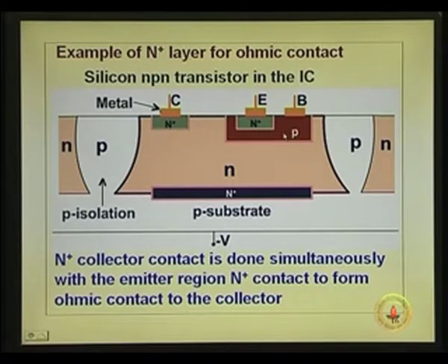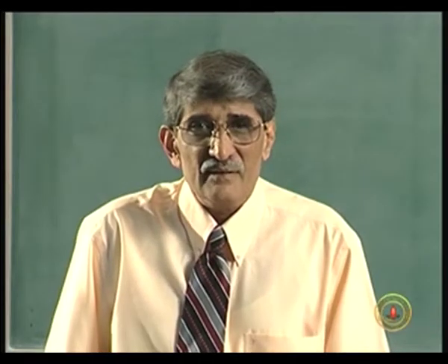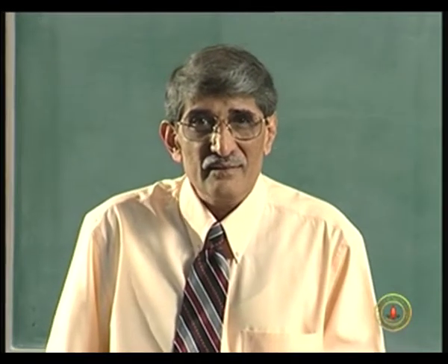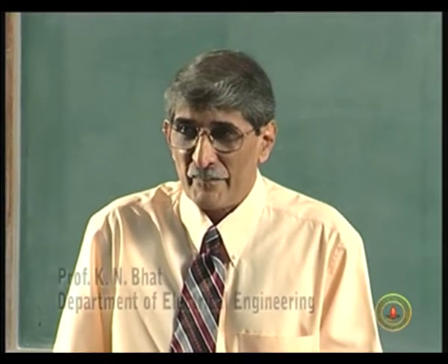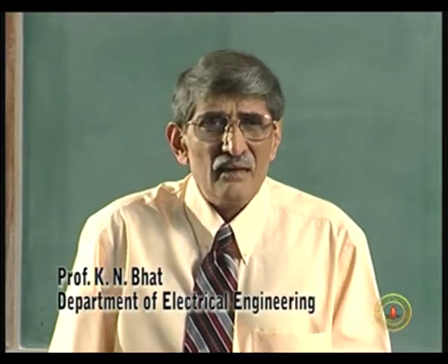But what about this n region that is base? Instead of P that will be n, you must put an n plus region, that has got to be a separate step. This is one of the difficulties when you want to make PNP transistors. In fact, if you carefully see, the PNP transistors are costlier than NPN because of that additional step of forming the n plus contact.